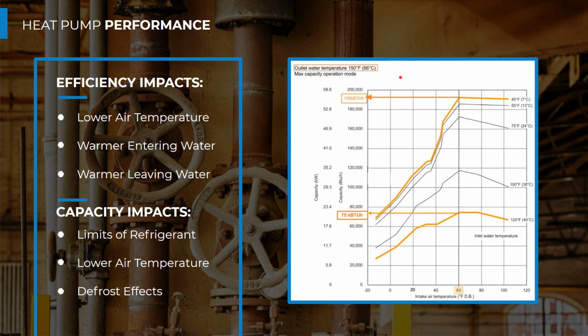You do want to be conscious about Legionella or Legionnaires' disease, and storing water at a higher temperature is arguably better for that. But it doesn't necessarily mean it needs to be stored at 150 in all regards.